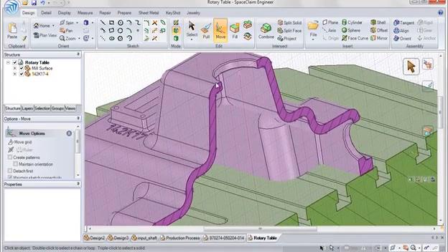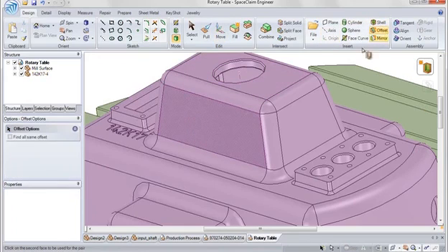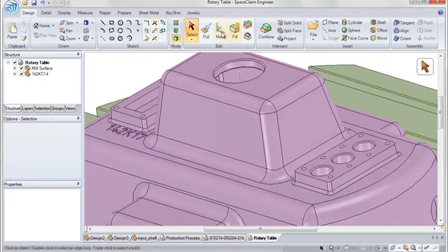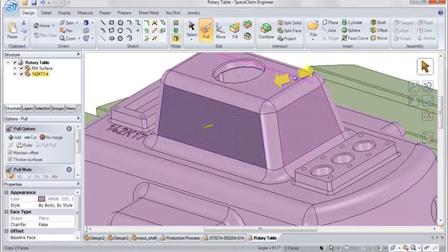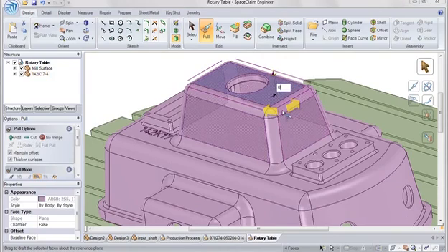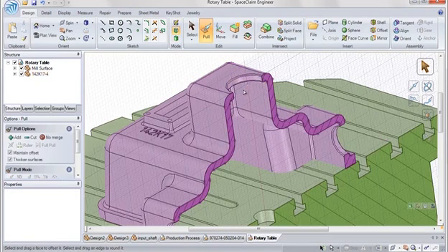Well, in SpaceClaim, to make sure that we're drafting both sides appropriately, I can use my offset tool to easily find all offsets of the same width. It'll go in and identify those all the way around the model, so that now when I go in to pull on all 4 of these faces to change the draft about the top face, when I change that to 0, it'll draft both the inner and the outer faces simultaneously. You can see that as I go back to a cross-section view.